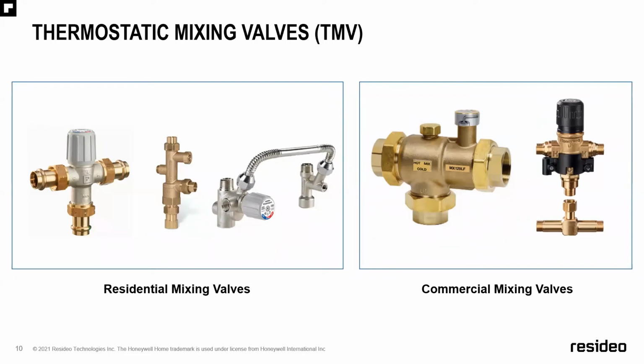So if you have a big 120 gallon plus tank type water heater that you're moving a ton of volume through, I would look at our commercial mixing valve, our AMX series. This also comes with a 1/2-inch recirculation port, and it's a true tempering valve, which means it can't be adjusted without having the tool, which is just a basic Allen wrench. A lot of inspectors in a commercial space want to see that it can't be tampered with, because if it is, and you get to a point where scald is an issue, there's a huge liability there. So that's huge value when it comes to the AMX series.